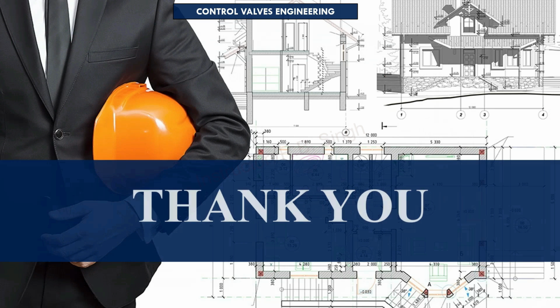So this is all about control valve characteristics. With the help of these characteristics, we will do the sizing, and we will see what the consequences are of different types of characteristics if you are not following them properly. If we do not use the proper characteristics, then there will be a lot of problems with valve functioning, just like sometimes noise, sometimes flashing, and choked flow. These kinds of consequences will be there.